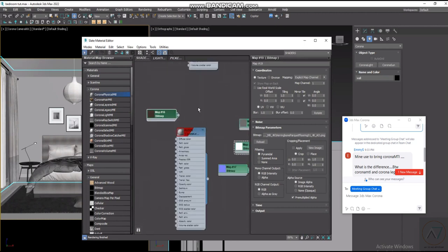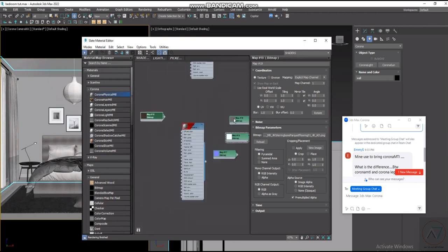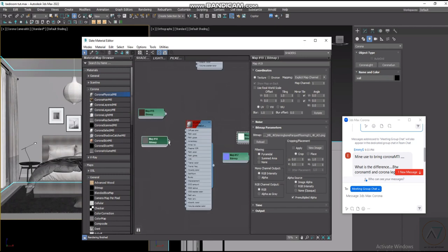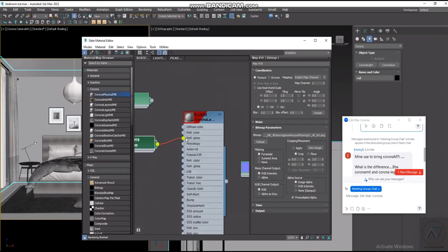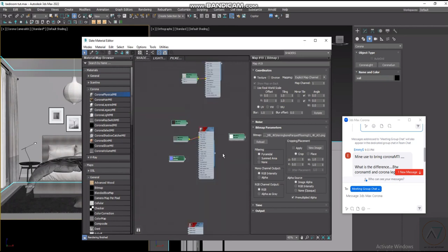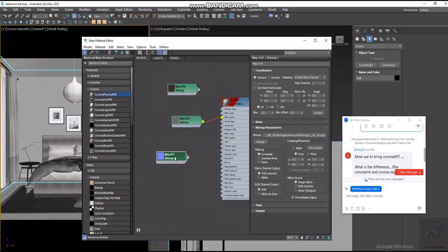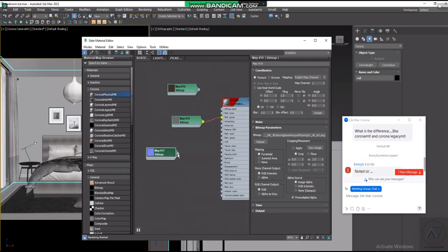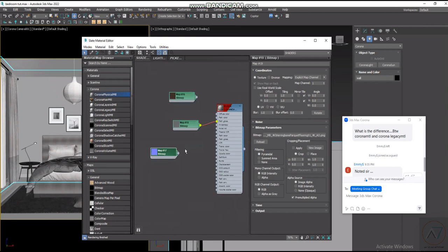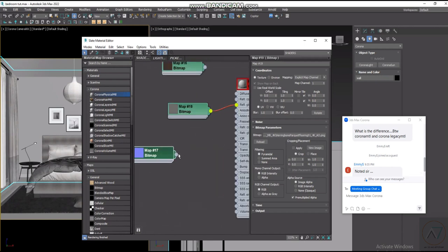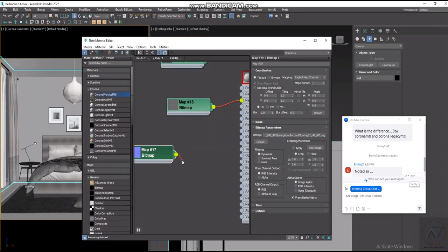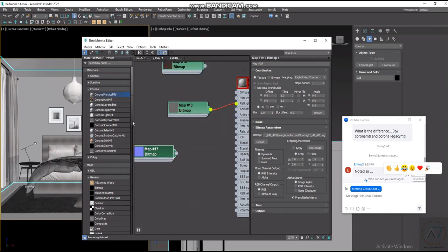It used to give you all this imperfection on your surface. So with this diffuse, this is our reflective. Just plug this reflective into the reflective glossiness here. Then this is your bump, this is your normal map. You don't just plug the normal map into the bump directly. It won't give you what you want, and it will even give you an error message when rendering. So for this, you have to plug it into a Corona normal.